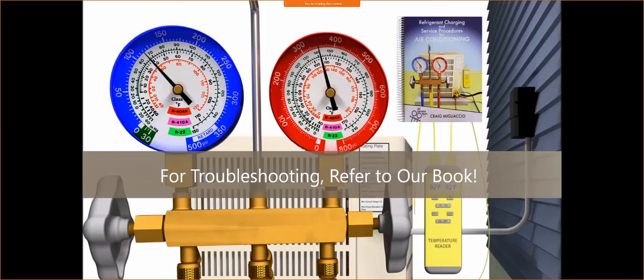As we have our warm air that comes across the evaporator, our evaporator's roughly about 55 degrees. That warm air, 70, 80, 90 degrees, whatever it is, as soon as it hits that, we're going to start releasing that latent heat. We're going to start to get that condensation start to form on our evaporator, and we're going to have water. Water's going to start draining out.